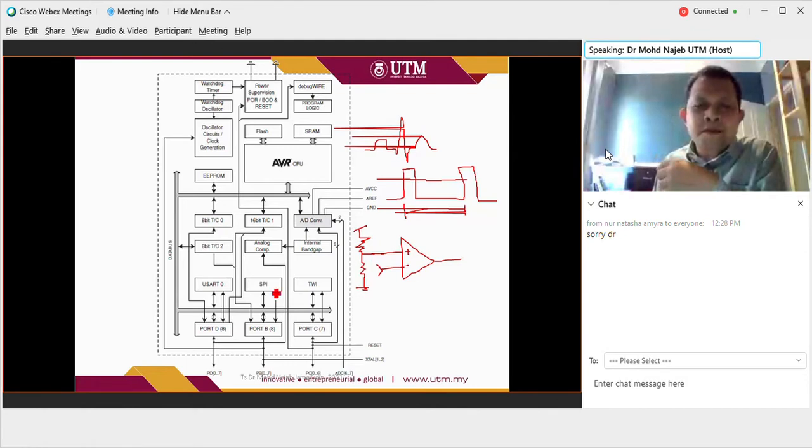So you can use this timer compare. When you use the timer compare, this feature will tell you, after you do some initialization and you have already started the program, when a certain time has been reached, right? And then from there, your program will be alerted, and you can do specific tasks triggered by that time, right?